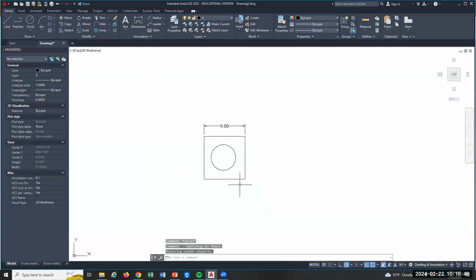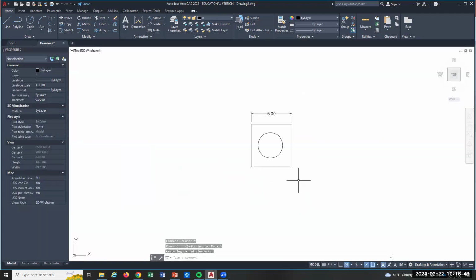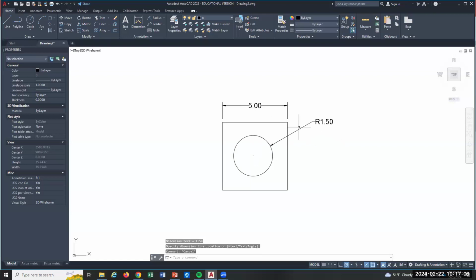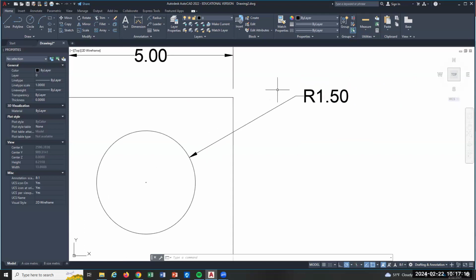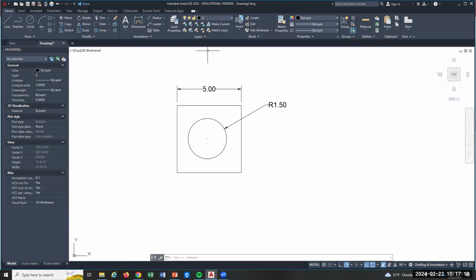In the end, typically you don't want anything in your template drawing wise. I actually leave something in there. So when I use my template, some kind of weird drawing comes in, but then I just erase it all. But it's kind of a reminder of what's ready and what's not. I'd probably stick that in there too. See, I don't like how close that is to the text. That's some kind of dimension offset, right? It's still some micro millimeter thing. I'd probably fix that because that's annoying. But other than that, that dimensioning style is looking pretty good, right?